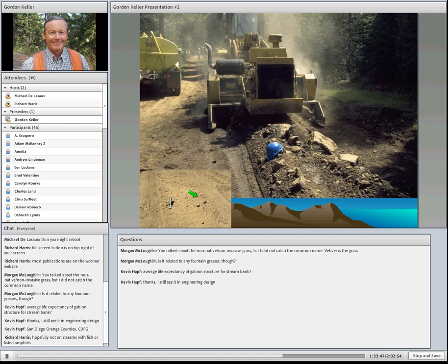In some test sections we've done with this, the Forester or some types of these mobile rock crushers, you can probably produce an aggregate, this aggregate here, that may be half the cost of an imported aggregate, but again, you get what you pay for. It either has a lot of fines in it, or maybe it's on the coarse side, but it's still cheaper than imported aggregate, though it doesn't perform quite as well. But at least you don't have really bony rock, which is hard to maintain.